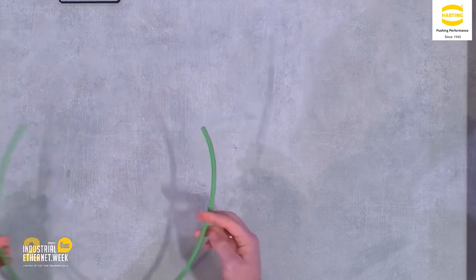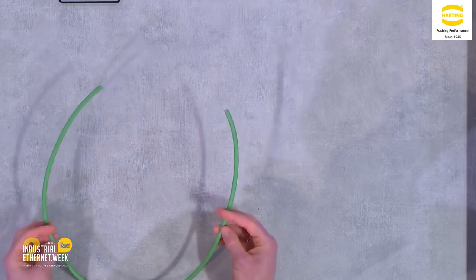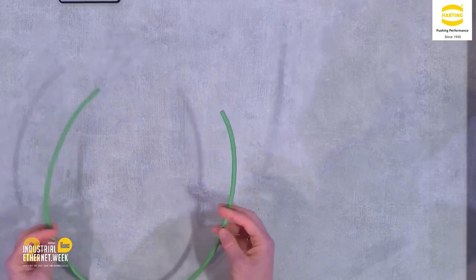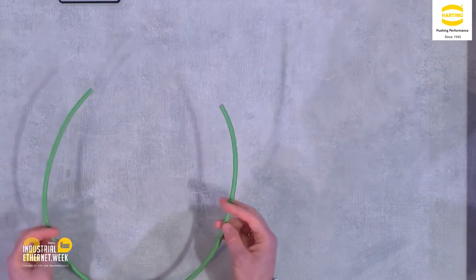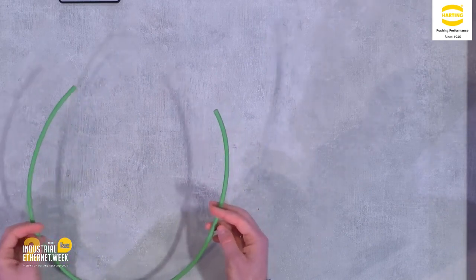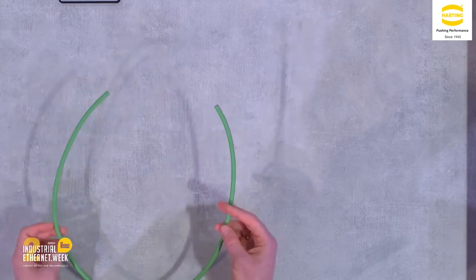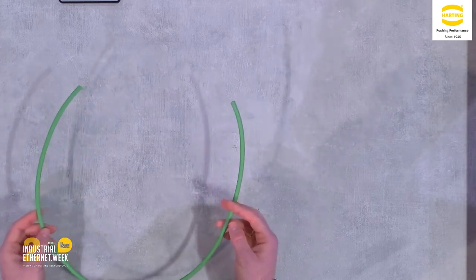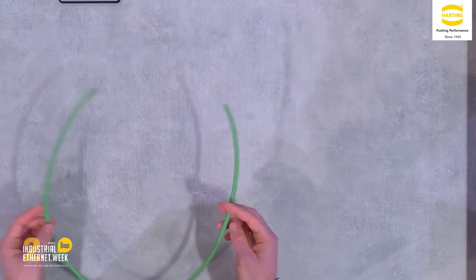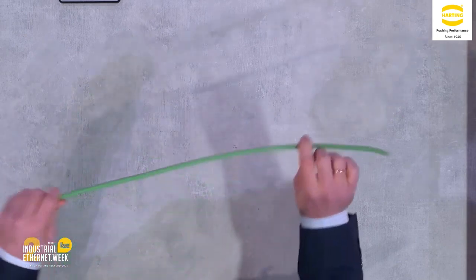So that's a robust but highly flexible design where 19-wire stranded conductors allow use in, let's say, normal industrial applications with high mechanical stress from torsion or repeated bending. We have PVC and PUR cable jackets available, which are flame retardant and halogen-free. For the normal movement in that application, there are 3 dimensions. We have first the torsion,